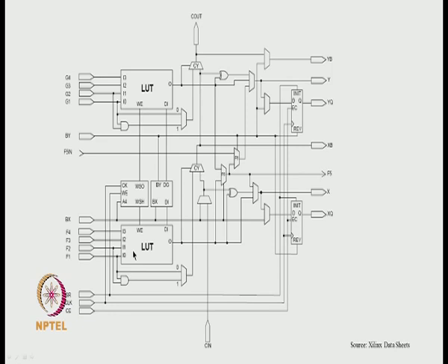Okay, so normally what you do is go to the core generator, which makes available the standard cores, so you can instantiate the distributed RAM. Sometimes you write in VHDL a case statement, like you say K is on say ABCD, and you say 000 output is something, 001 output is something else, for all the 16 possible values.